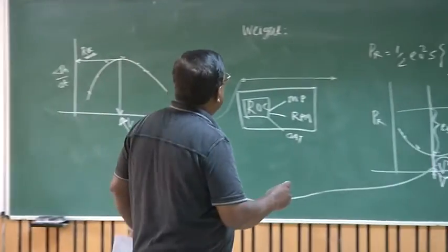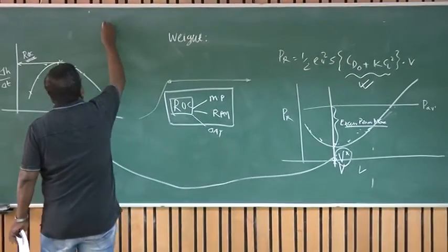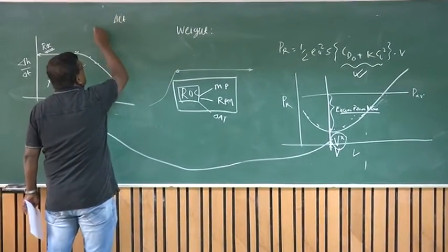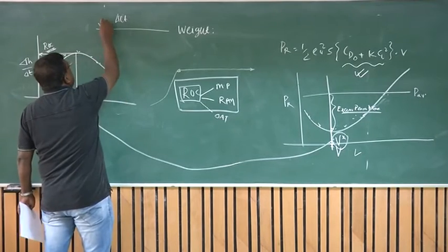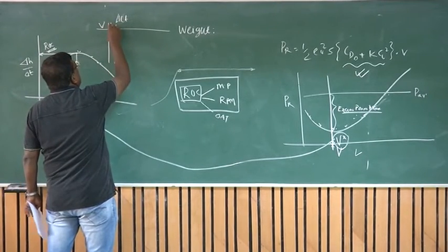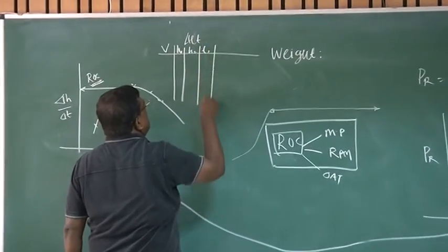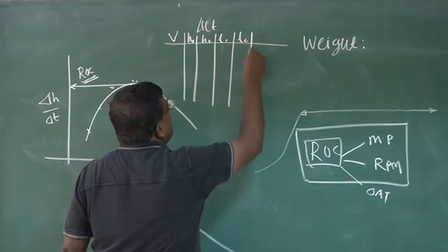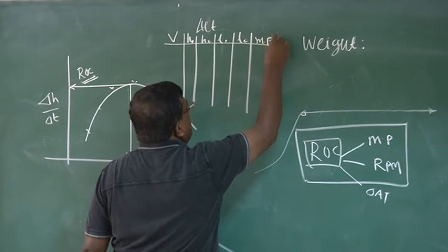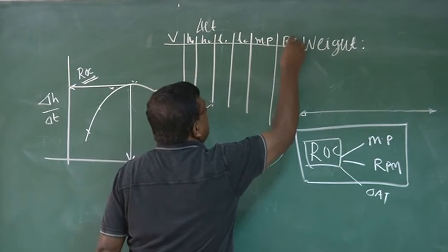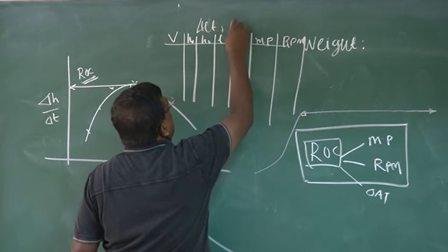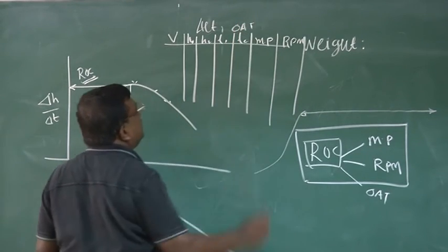I repeat again, you go to an altitude, and for different speeds, you note down H1, H2, T1, T2, and also, which I missed, you note down manifold pressure and RPM, and of course you will always note down outside air temperature.